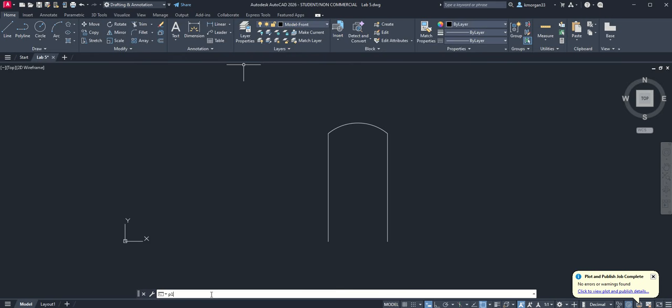And we did the polyline, PLINE. Some people call it pline, but it's the polyline. The next one is poly, and then gon, polygon. And then we did the rectangle, so RECTANG. These are all the commands that we did in this lab 5.